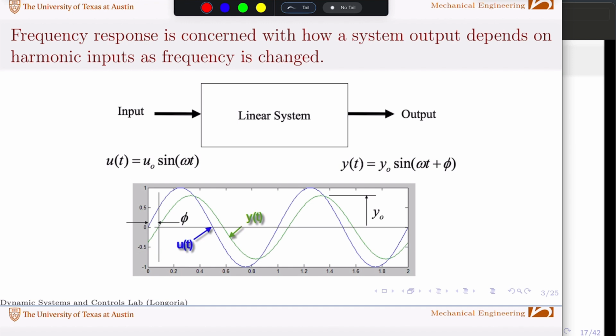So the nice thing about it, if this is a linear system, remember your Fourier concepts, any signal, if it's periodic, can be composed of many sinusoids. So these principles hold for any system that you can approximate as linear, and if you can understand how the input and output relate through a representation of some kind, what we call a frequency response function, which is what we'll talk about, an FRF, then that tells you how to relate the input and output. So it's a very useful concept, and I'll show you some examples of how it's used.